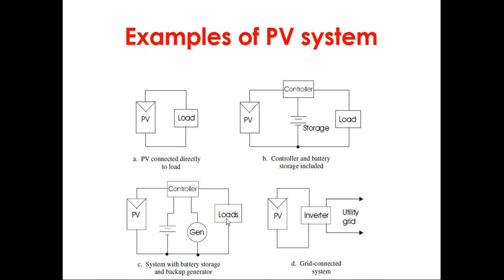If there is still more load, then 1 plus 2 will both satisfy the load demand. If there is high load, or during night time when PV is not there, then the generator has to be turned on. So the generator acts as a backup. Obviously, at all times, the generator is not the only option. We are using batteries also as a backup medium.